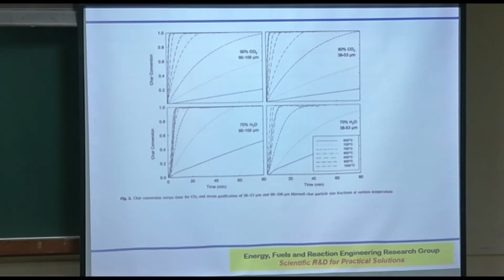Sending the reacting gas from the beginning is not going to help anyway, because at 100, 200, 300, 400, 500, 600 degrees nothing is going to happen anyway until it reaches a certain temperature. So only when it has reached the temperature do you start injecting. So this is how this was done.